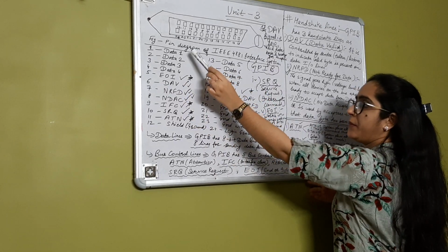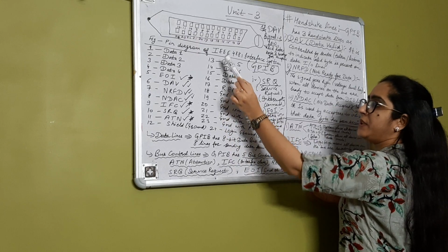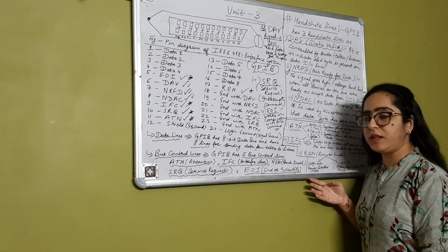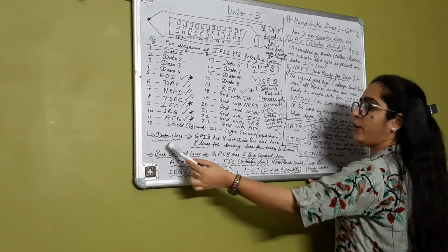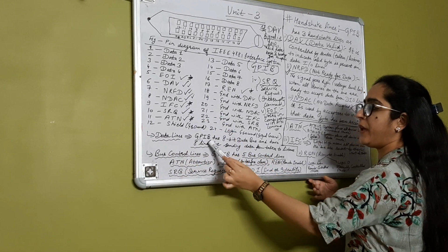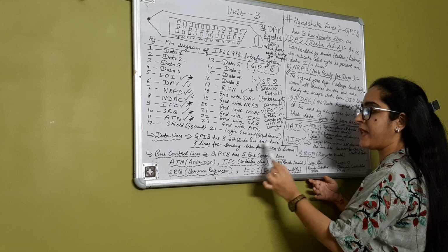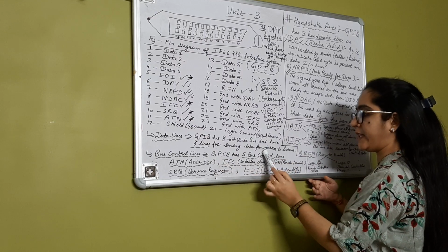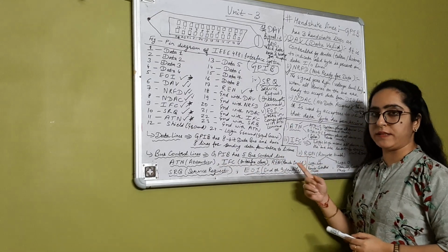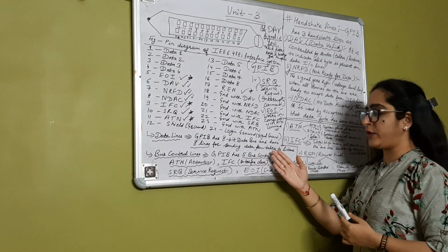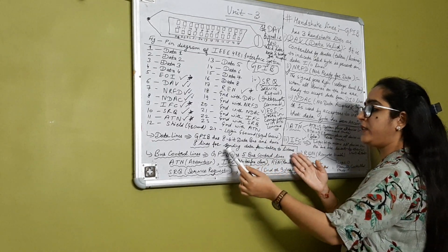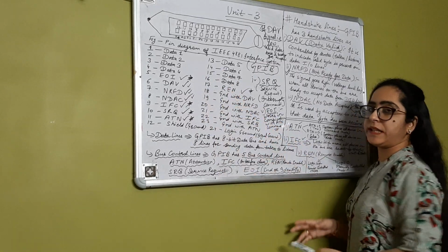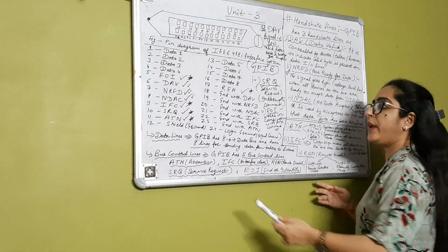If you look, pin number 1 to pin number 4 and pin number 13 to pin number 16 give us the 8 data bus lines. GPIB has an 8-bit data bus, with 8 lines for sending data from talker to listener. Any data which the talker wants to send to the listeners will be sent through these data bus lines.